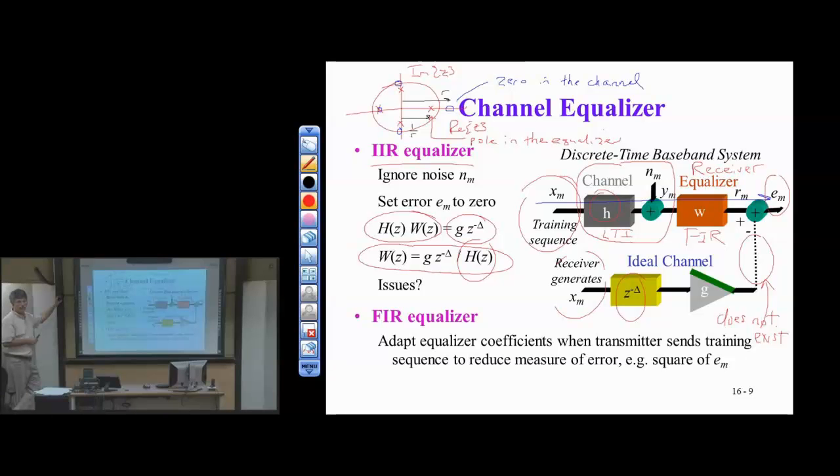So why do we care about phase response? Well, it depends on the modulation method. For QAM, phase really matters. For PAM, not so much. A 45-degree error in PAM, I'm fine. QAM is sensitive, and I have to get a smaller phase error as my constellation grows in size. So it's possible you don't care much about phase.